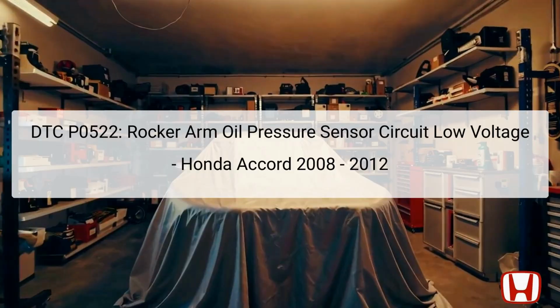The DTC P0522, which stands for Diagnostic Trouble Code for Rocker Arm Oil Pressure Sensor Circuit Low Voltage, indicates an issue with the rocker arm oil pressure sensor in the Honda Accord models from 2008 to 2012. This sensor plays a critical role in regulating the engine's oil pressure, ensuring that the oil flows efficiently to various components of the engine, particularly the rocker arms.